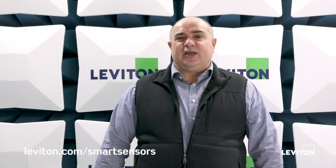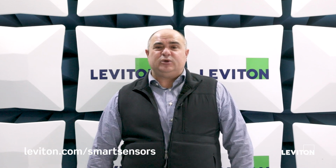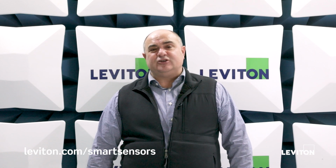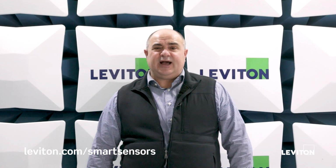The other topic that I want to make sure we cover and that needs to be taken into consideration as we develop these different solutions is receptacle control, sometimes referred to as plug load control. Now, currently, both ASHRAE 90.1 and California Title 24 Part 6 have required plug load control ever since the 2013 code cycle. With regards to the International Energy Conservation Code, that has just been instituted into the 2021 IECC.